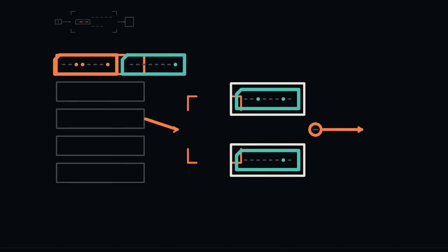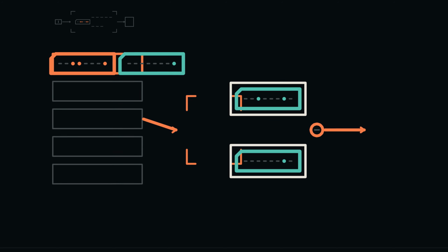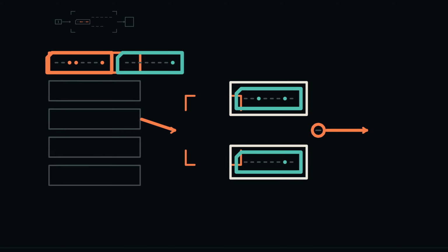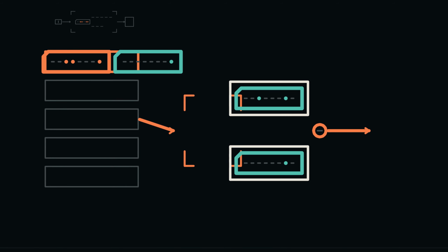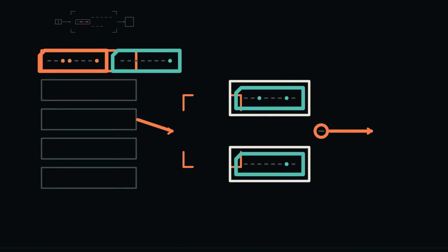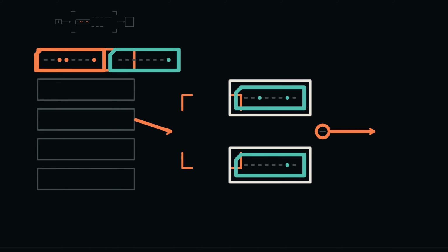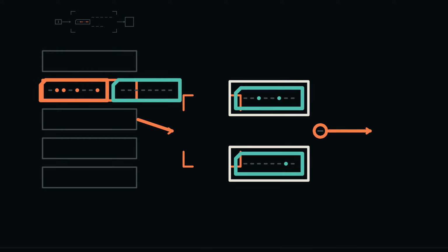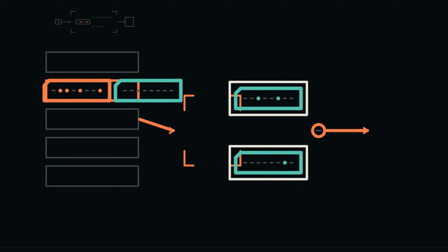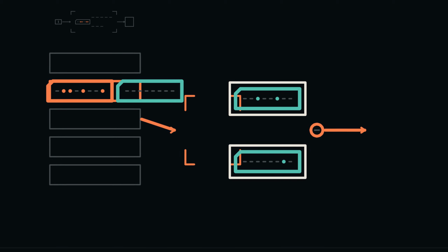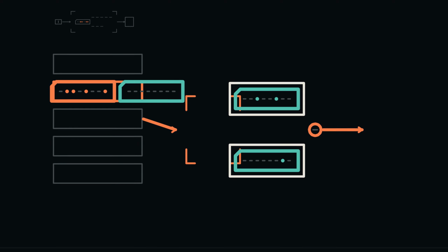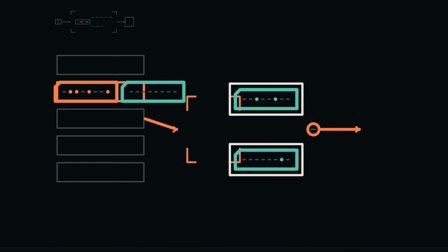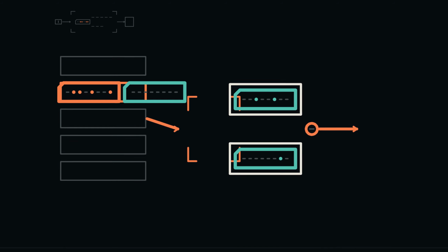Notice what made each answer. Arithmetic determined the result, the result determined the flags, and the fixed instruction width determined the fall-through address. One glow on the screen would have hidden those separate causes. Now compare R0 with 0. Predict whether R0 changes. Compare performs a subtraction only to set flags. It does not write the computed result back into the register. R0 therefore remains 2, and the 0 flag remains clear because 2 minus 0 is not 0.